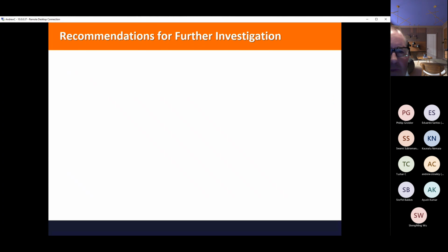Part of the report should say what recommendations you require. So often the process of inspecting a building won't be a one-off. You will have a series of inspections. So you'll start with a plain investigation, a visual survey of the outside and the inside of particular areas. You will also do a desk study as well, if you can. Pick out the drawings either from the client or from the council file.